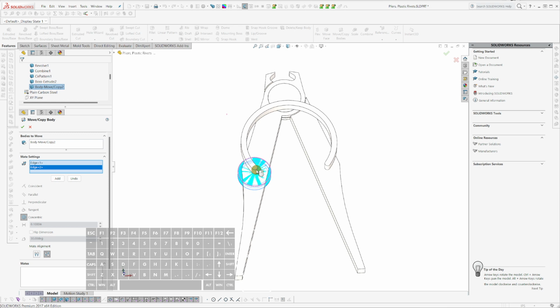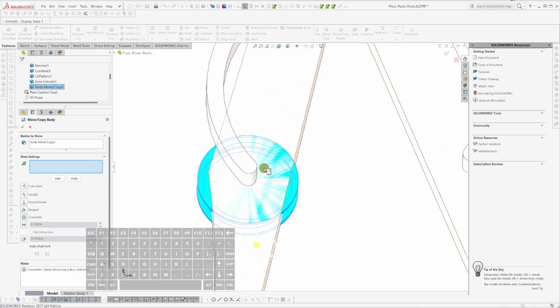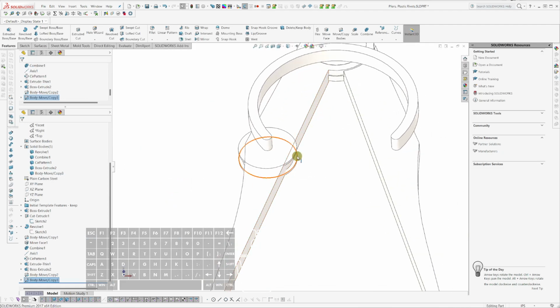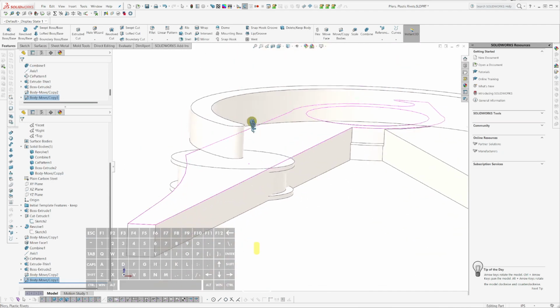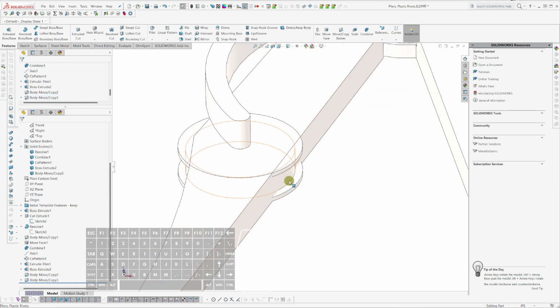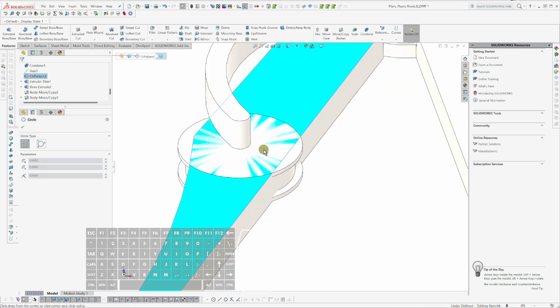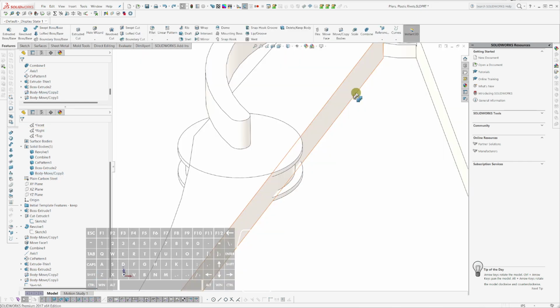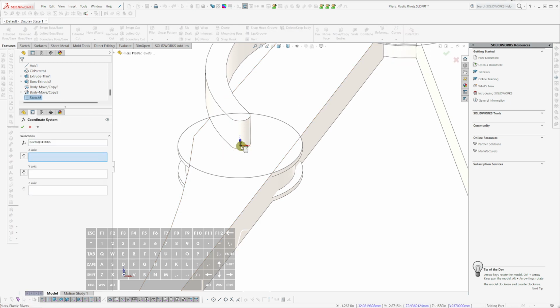What do you call it? Concentric. All right. Now, obviously, it's too big, but I can do a non-uniform scale to get it to a more appropriate size. And I also need to join it up to here. But anyway, I'm just going to project this geometry, and so now I can rebuild that. I'm going to turn my sketches on to see that center point. I'm going to use that to create a coordinate system to scale the piece by.